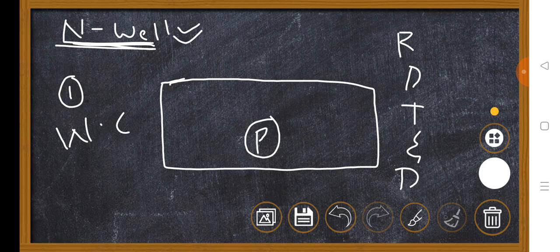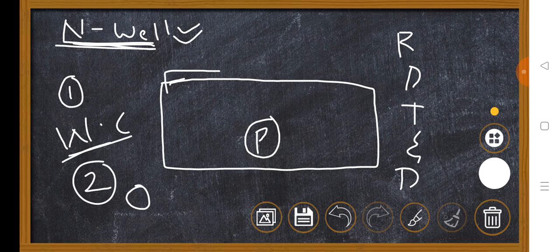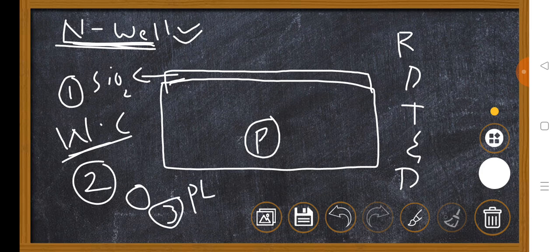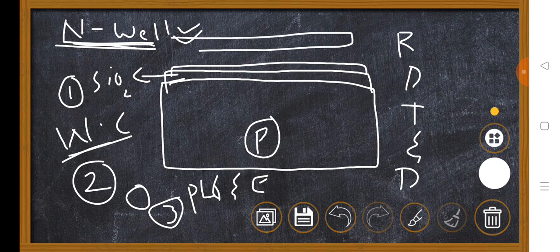Now observe very carefully. After the first step, wafer creation, what will be the second step? Absolutely, oxidation. As usual, we have to do the oxidation. After that, we observe that there is a silicon dioxide layer. After these two steps, what will be the third step? Absolutely, the photolithography and etching step. I hope you are clear. Then you have to form a photoresist, and you have to take the photo mask. After that you have to expose with UV light.